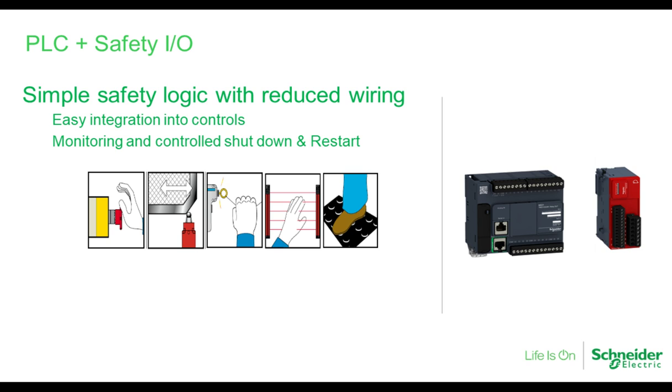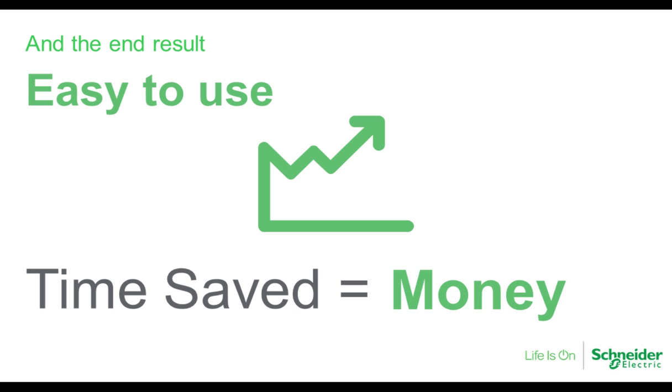I'm not showing all the pictures that are available. There are other safety modules that can be added to PLC systems, some of which are more remote, and they are programmable, and they do have logic employed in them. Some of them are designed a little bit more for process. Others are more for machines, especially around robotics. But that's another thing to be aware of, too, is that some of your standard PLCs can have safety functionality added to them.